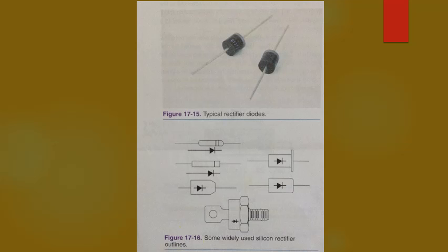Silicon rectifiers have high forward and reverse current ratios. This is the ratio of current allowed in the forward direction compared to the current allowed in the reverse direction. They can achieve rectification efficiencies of greater than 99%. These rectifiers are very small, light, and built to last a long time. In addition, they can be made resistant to shock and mishandling. Silicon rectifiers do not decay with age like a vacuum tube rectifier does.